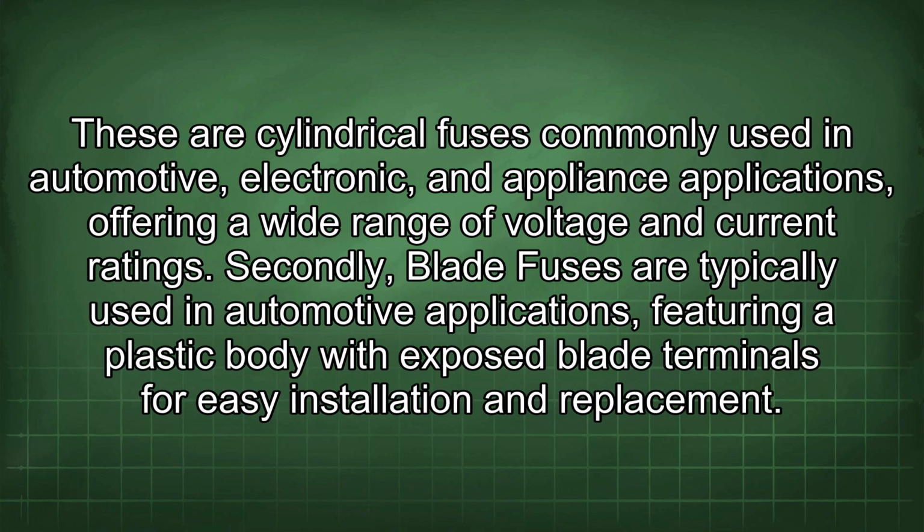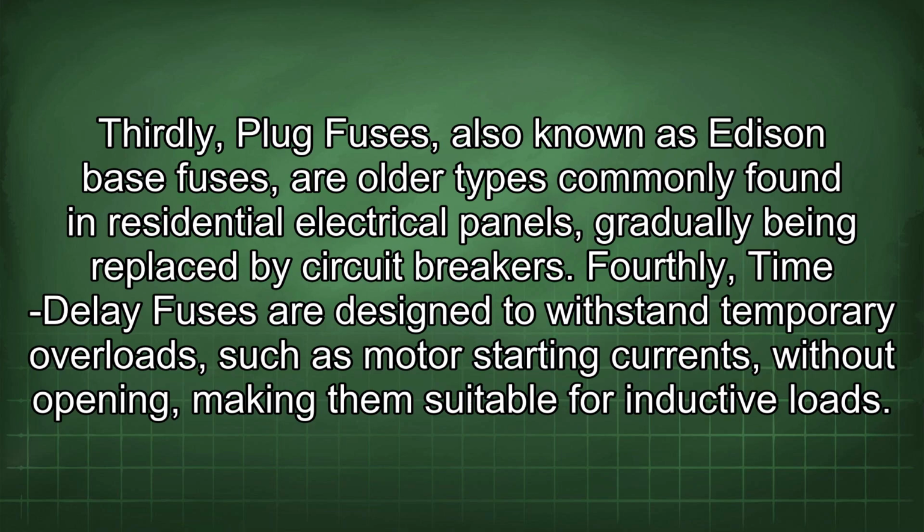These are cylindrical fuses commonly used in automotive, electronic, and appliance applications, offering a wide range of voltage and current ratings. Secondly, blade fuses are typically used in automotive applications, featuring a plastic body with exposed blade terminals for easy installation and replacement. Thirdly, plug fuses, also known as Edison-base fuses, are older types commonly found in residential electrical panels, gradually being replaced by circuit breakers.